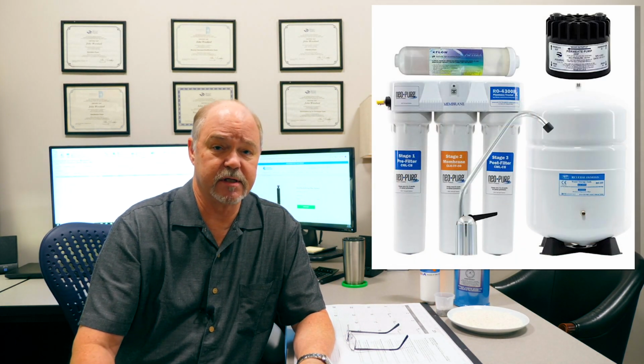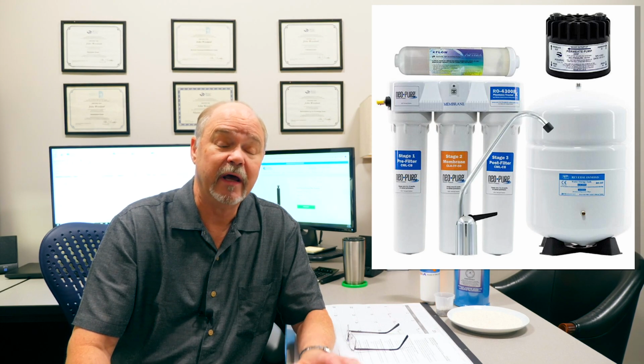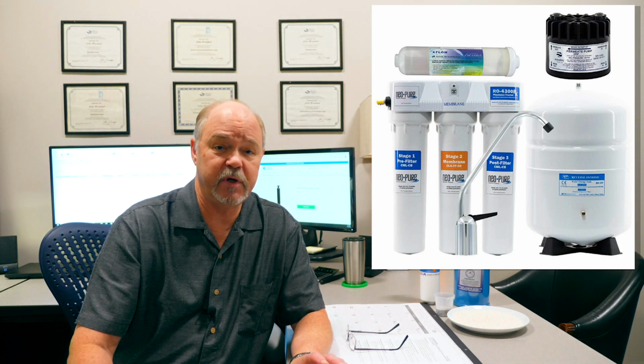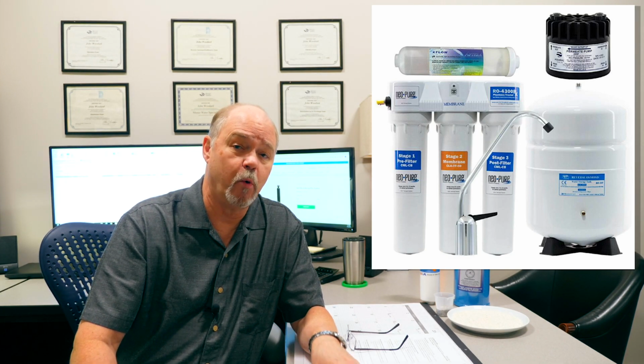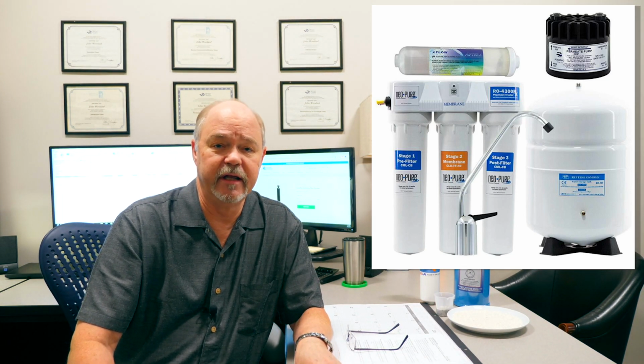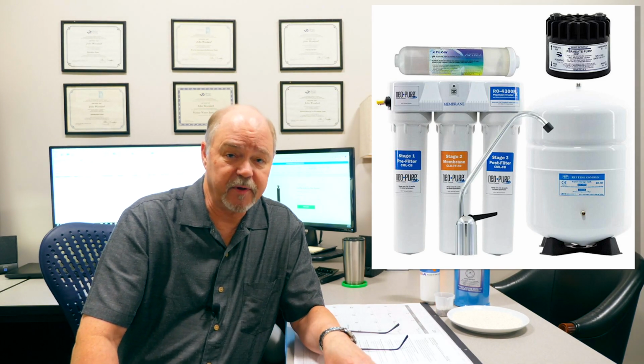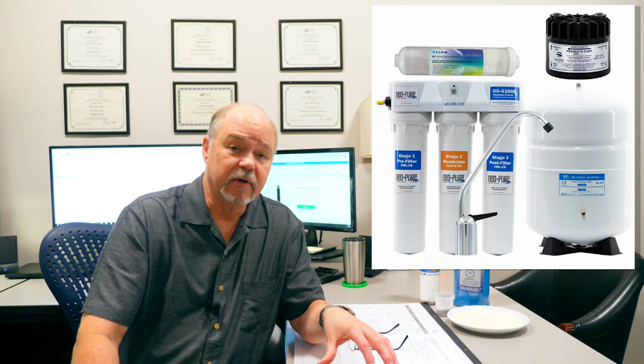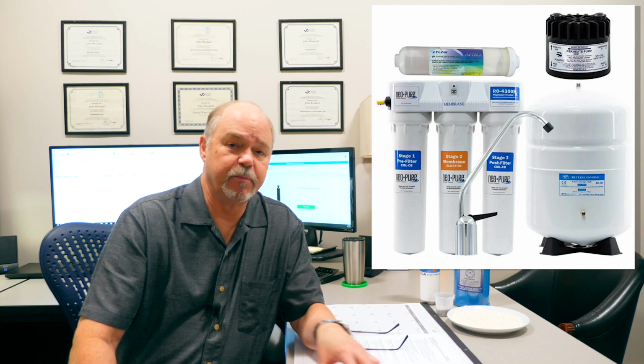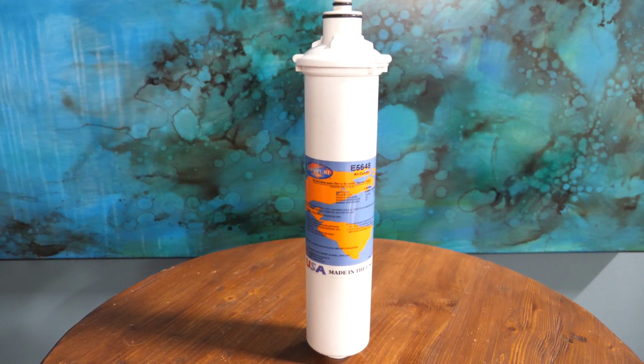Now, if we're talking about point of use type corrections, reverse osmosis is an example where we might use a cartridge type of pH adjuster. Reverse osmosis will reduce pH by 1 point. And the reason it does that is it's stripping alkalinity out when it takes inorganic minerals with it. By dropping that pH a full point, a lot of customers like to add something to pull that pH back up. And they do that with a calcite cartridge.